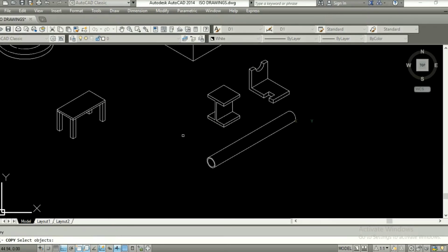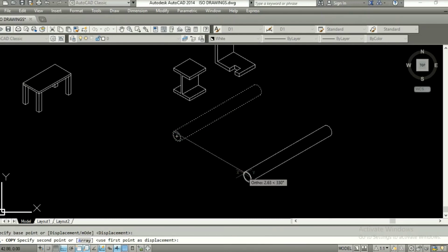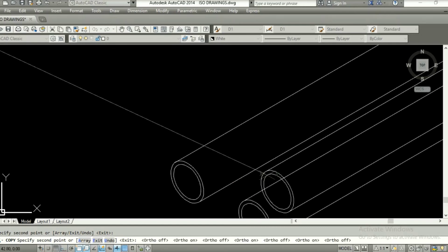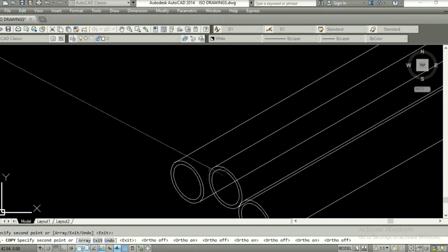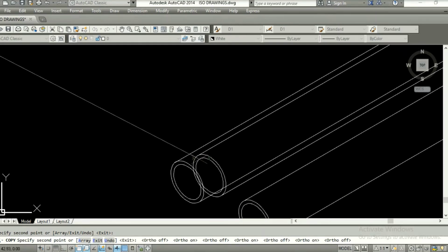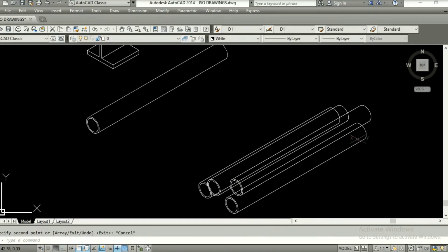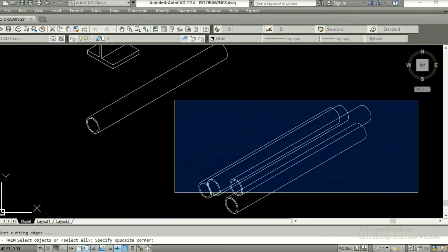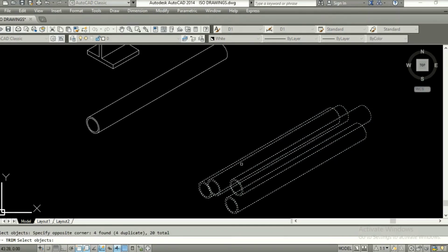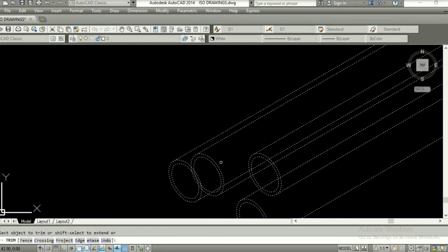Copy, cross again, see how cross works. Copy it here, place it one above the other, press F8, so it allows you to move carefully. Keep another above the other, see here, and make it look very natural. Okay, now trim command works wonderfully here. Select the whole lot and trim. Again, I told you, need to be very careful.